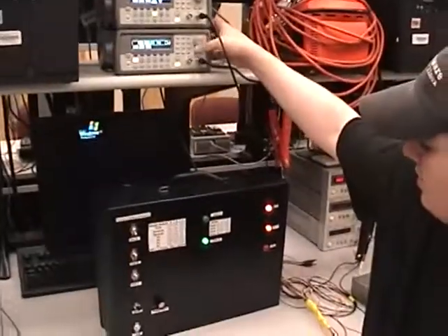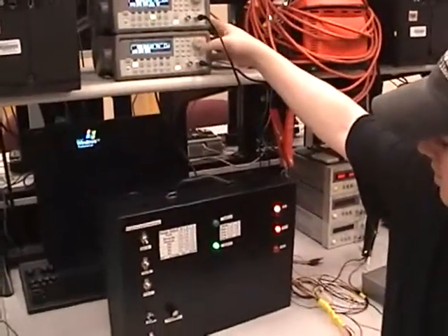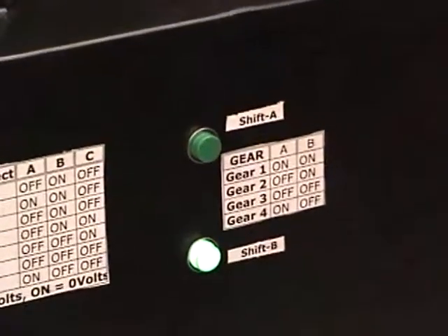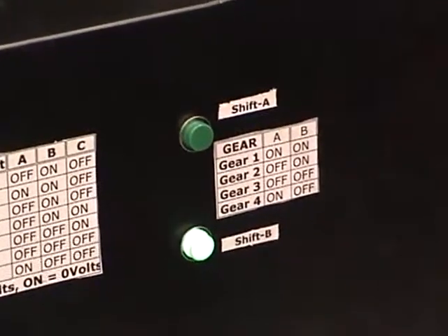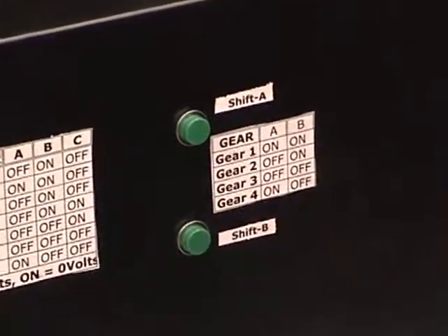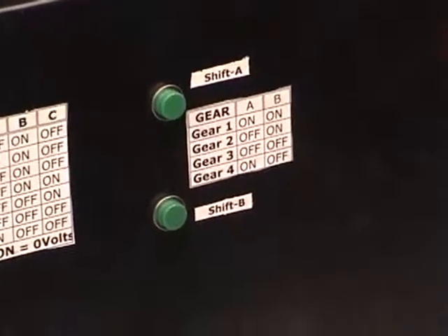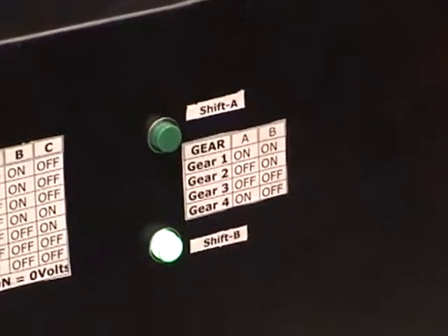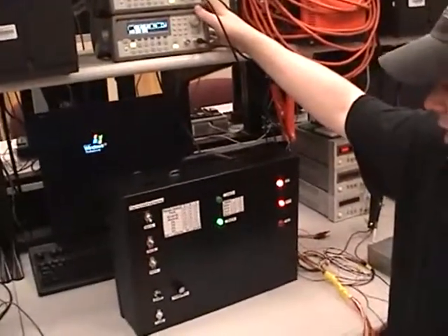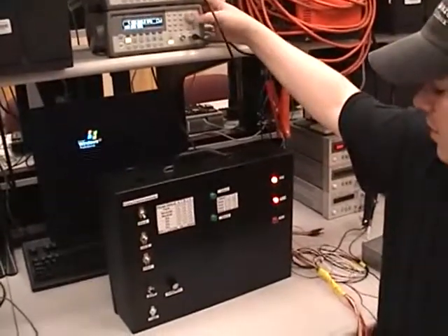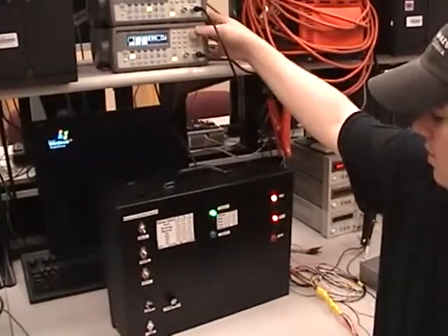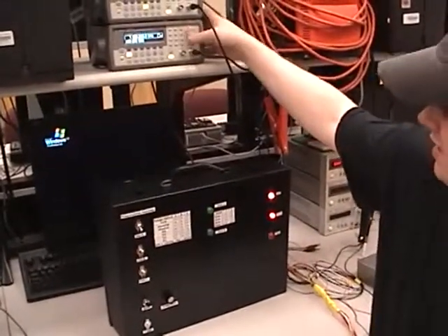And this occurs for all gears, so we'll go ahead and try around 1,000. So if we make it just go into third gear, which you saw right there, and there's no delay here, it occurred right then, you can see that we had to drop down a whole 100 hertz before it actually went back to its previous state, and that occurs for all of the gears. So you can see that.